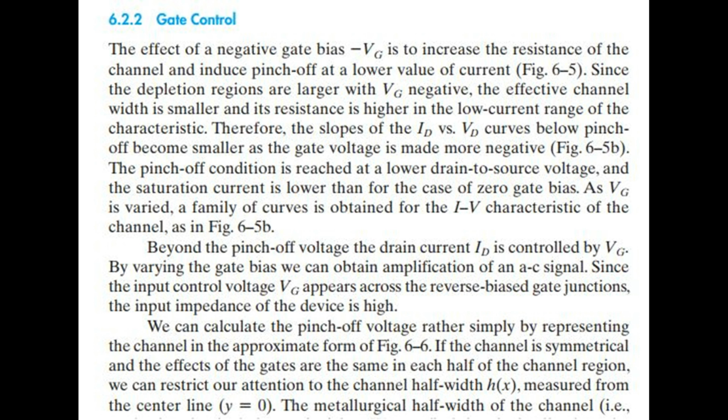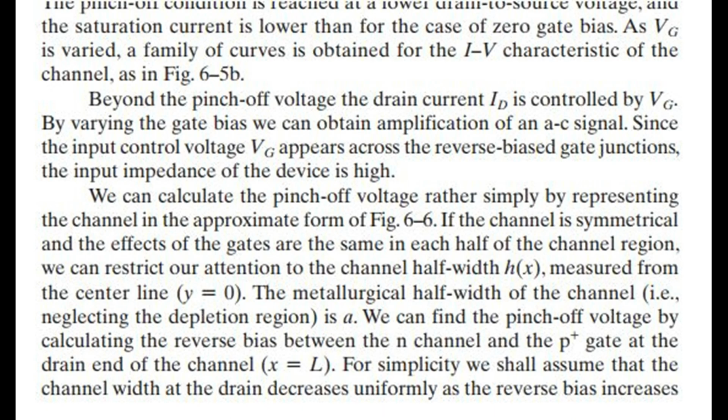We can calculate the pinch-off voltage rather simply by representing the channel in the approximate form of Fig 6.6. If the channel is symmetrical and the effects of the gates are the same in each half of the channel region, we can restrict our attention to the channel half-width h(x), measured from the center line, y equals 0. The metallurgical half-width of the channel, i.e., neglecting the depletion region, is a. We can find the pinch-off voltage by calculating the reverse bias between the N channel and the P+ gate at the drain end of the channel, x equals L.